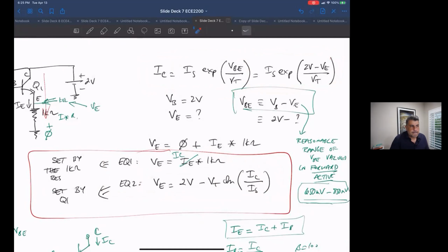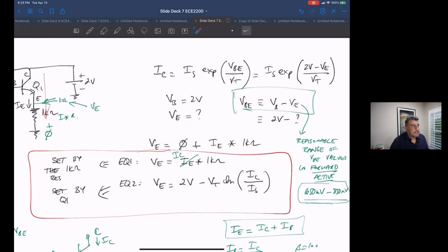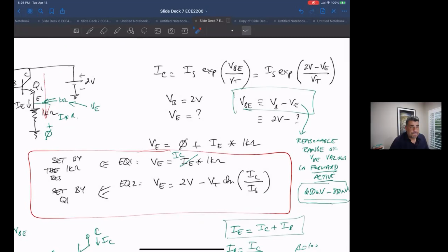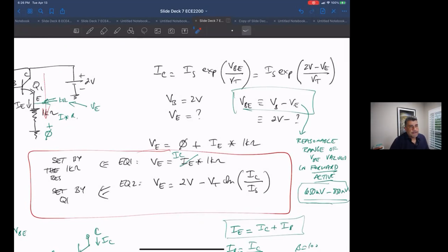Does that make sense, Nelson? Did you ask the question, Nelson? Yeah, that makes sense. Basically, you're just solving for I sub C. Sometimes you might be solving for V sub E too; it depends on which one you need. For this problem, you just need I sub C.